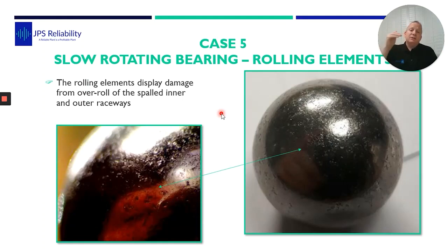So this is a really good find. And now we know at a certain level in the time waveform of a certain pattern, we know the bearing is failed. As to how long this bearing would have lasted, it's at such a high risk that it could catastrophically fail, that it is a good call to pull it out.